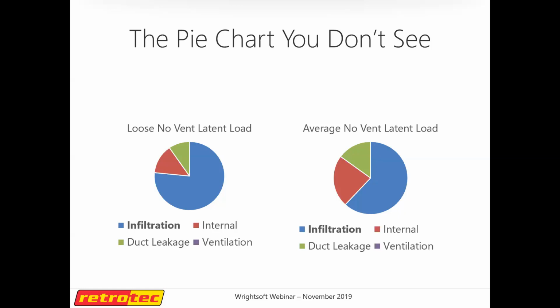only it's even worse because infiltration is also temperature and pressure related when you're talking about gases, of course. The temperature differential is going to be higher in the wintertime than in the summertime. So to make that even worse, instead of it being 2.5 times worse on the heating side, you have more actual infiltration happening in the wintertime, and so you have an even bigger load in the winter versus the summer.